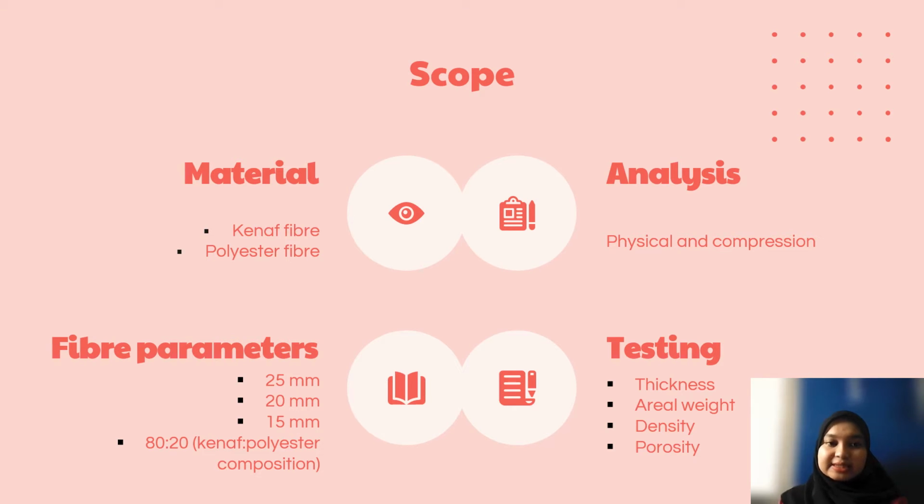Physical analysis such as the test for thickness, areal weight, density and porosity were conducted on the nonwoven web produced, as well as the compression strength test to evaluate the physical qualities of the nonwoven web that was produced.